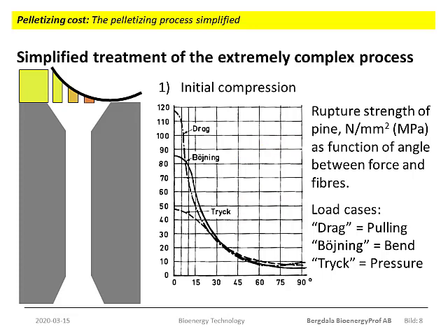The diagram covers 3 different load cases: axial tension, static bending, and compression. To generalize, one can say that the starting point for the 3 curves, the intersection with the y-axis, will be reduced to about half if the moisture content is raised to the fiber saturation point. Fiber saturation is about 22% moisture on a wet basis. The values at the right-hand side of the diagram, loads perpendicular to fibers, will not change significantly with moisture content. The diagram is copied from a classical Swedish material handbook, and I use it not because it is the most accurate, but because it contains lots of information and I had it available in my bookshelf.